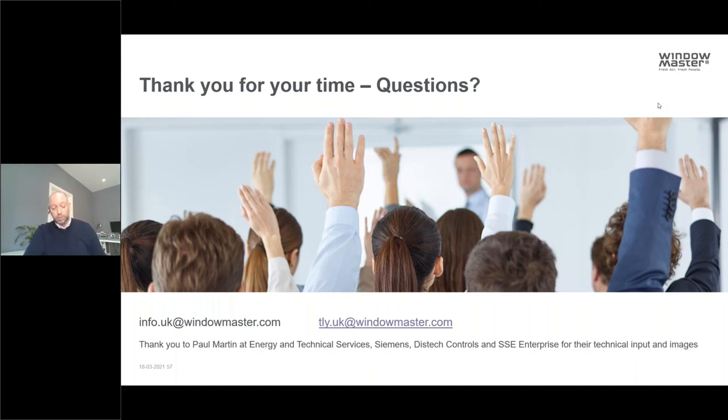And of course, at the moment, we're also having to adjust some of our control routines to use CO2 as a metric for general air quality and ventilation rates because of COVID. Yeah, there are lots of new sensors coming out, which will help us to adapt our systems to optimize the building depending on what circumstances are, whether it's a pandemic or non-pandemic situation, or whether or not we just want to deliver really healthy, comfortable, low carbon environments.